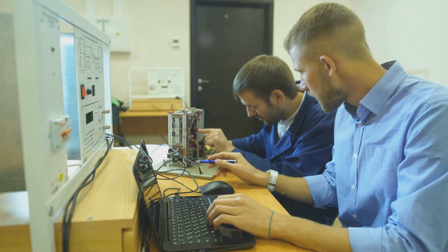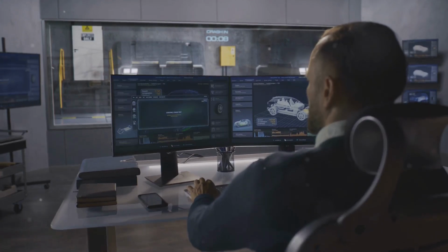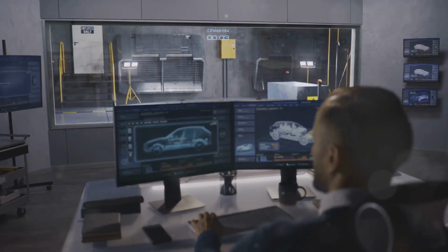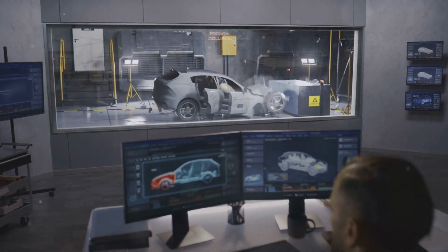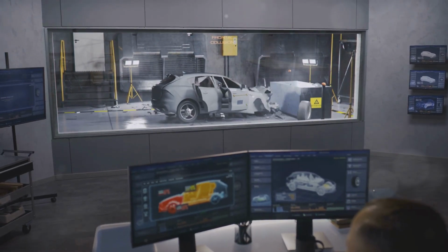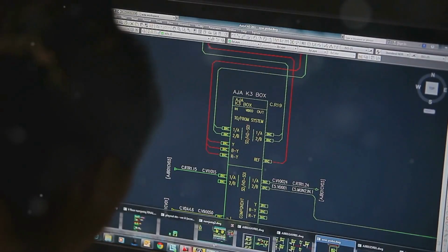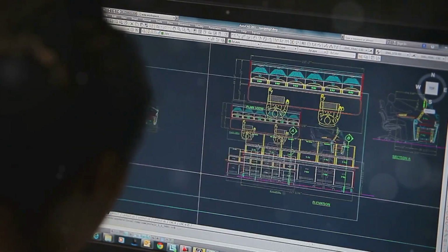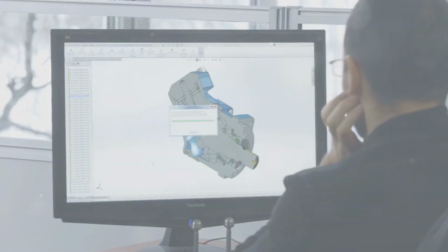Finally, establish the system coupling. This crucial step links the mechanical and fluid simulations, allowing them to exchange data and influence each other. Define the interface between the fluid and structure, specifying how data is transferred.